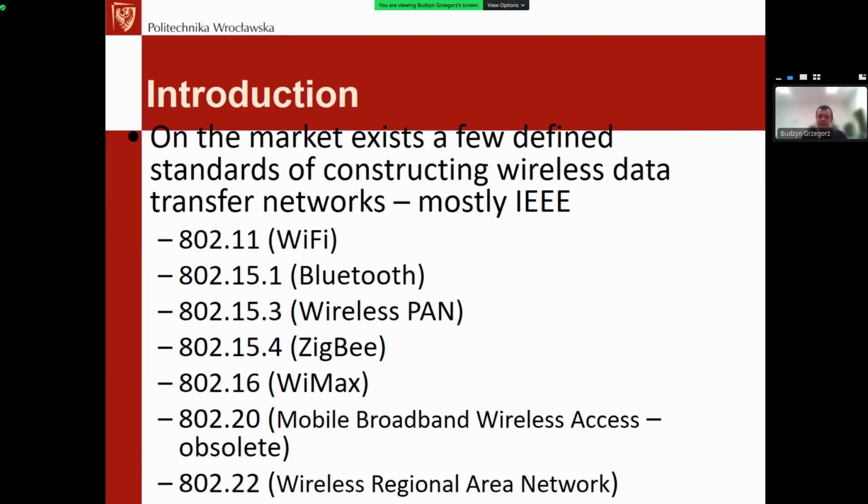In wired communication, it's either single-ended, twisted shielded pair, or fiber solutions. These are the options we have, and of course they differ a bit in capabilities. We can have higher throughput in fiber, lower in single-ended non-shielded cable, but the differences were not really great.